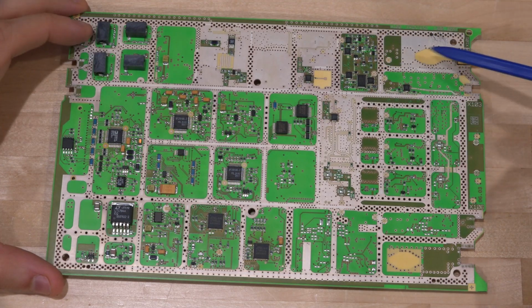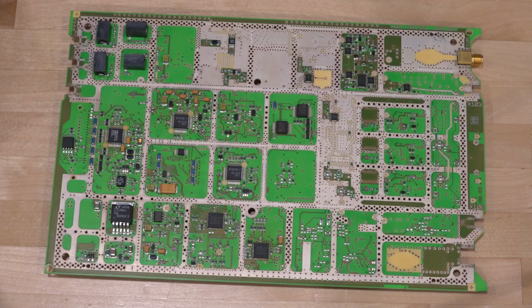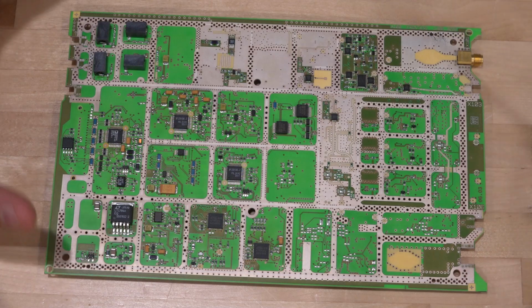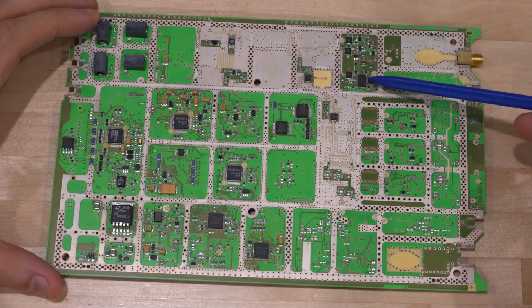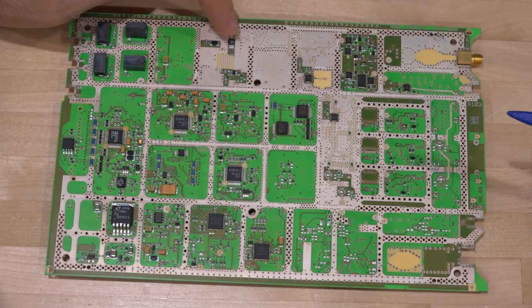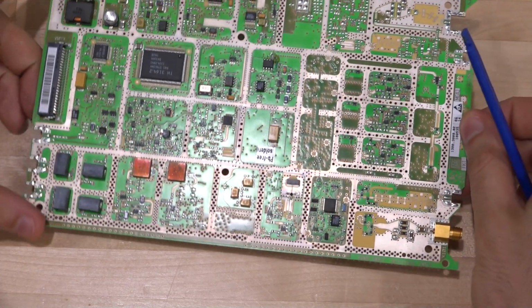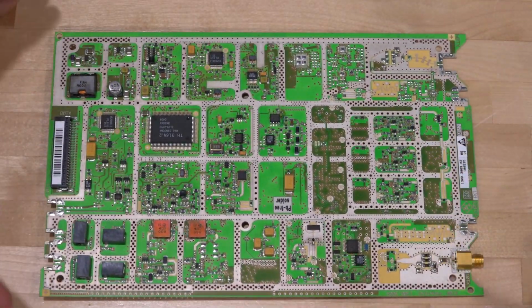So this is probably where the input comes in and gets split into multiple different bands, and those bands are responsible for different conversion stages depending on what input frequency you have. Some switches here. This is probably an attenuator, a programmable attenuator. This is most likely a mixer over here, one of the main mixers of this instrument. Yeah, looking good. Okay, so that was kind of an ad hoc analysis.